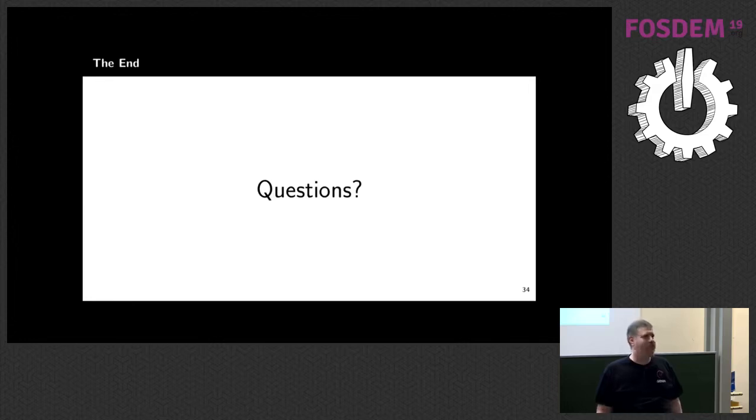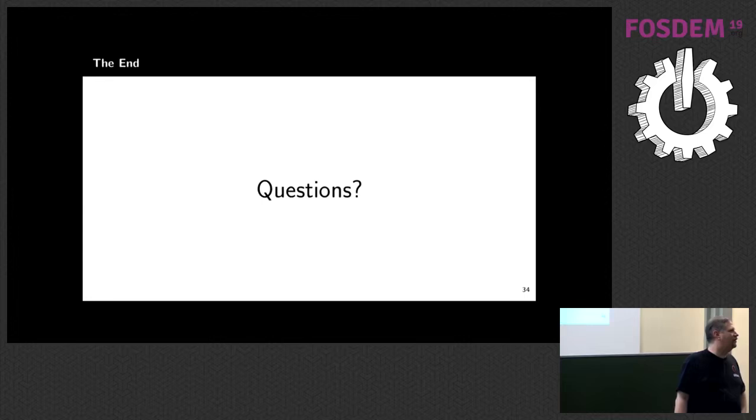Yes. I would just like to make a bit of a counterpoint to that. So I'm working on the FPGA tool stuff, and RV64GC is a pretty big ISA, because you basically got to have hardware floating point, and that's not very fun to implement on an FPGA. Even with an ECP5, that's going to be most of your FPGA gone, whereas RV32 is something that can very nicely fit on an FPGA and run quite well.